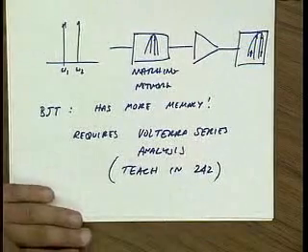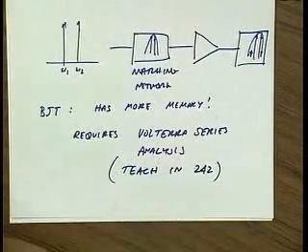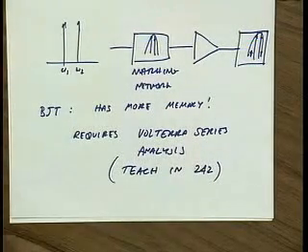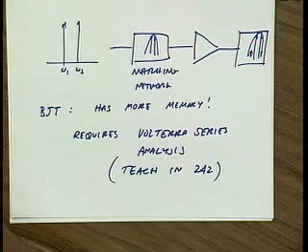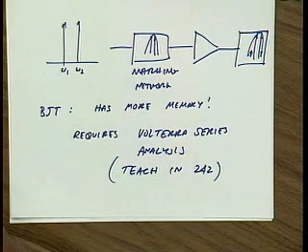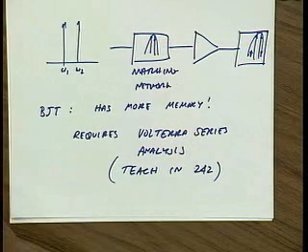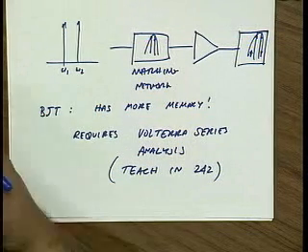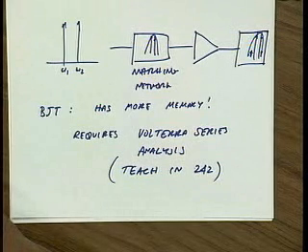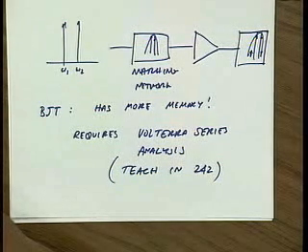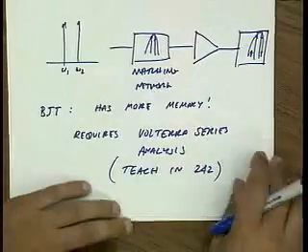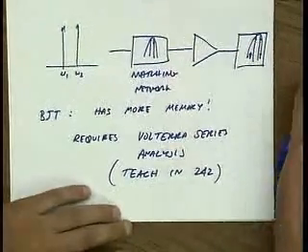But it lets you take into account the memory effects in a bipolar. What are some of the memory effects in a bipolar? Exactly. It's the tau F. It's the diffusion capacitance. You have junction caps just like you do in a MOS, but then you have this diffusion capacitance, which in combination with the junction capacitances makes the device have memory. Okay? Any questions?